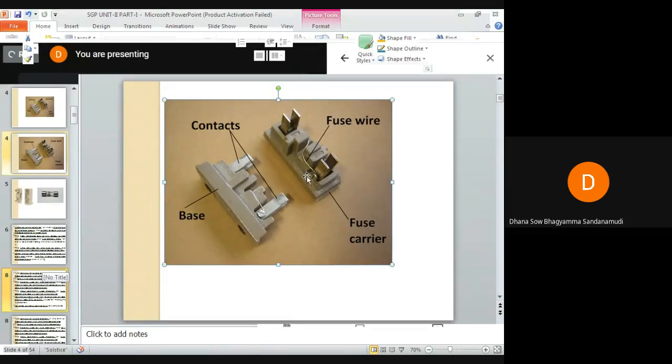Okay, a fusing wire is nothing but a fusible element. It will have a low melting point, low ohmic loss, high conductivity, low cost, and it is free from deterioration. The most commonly used materials for the fusing element or fusing wire can be lead, tin, copper, zinc, or silver. In general, in your laboratories, you can see a copper wire or a silver wire.